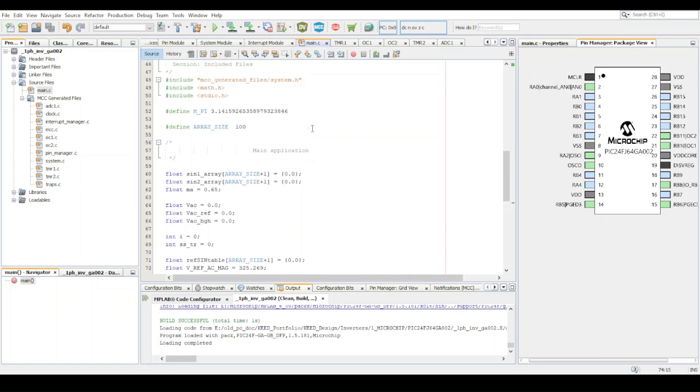basically the arrays are initialized. In this case, I'm utilizing a 100 element array. So the resolution is not that high. There's a reason I chose such a low value. Typically you want this value to be, I suppose, 400, where you have 200 every 10 milliseconds, and obviously 400 for the 20 milliseconds in the case of a 50 hertz sinusoid frequency.